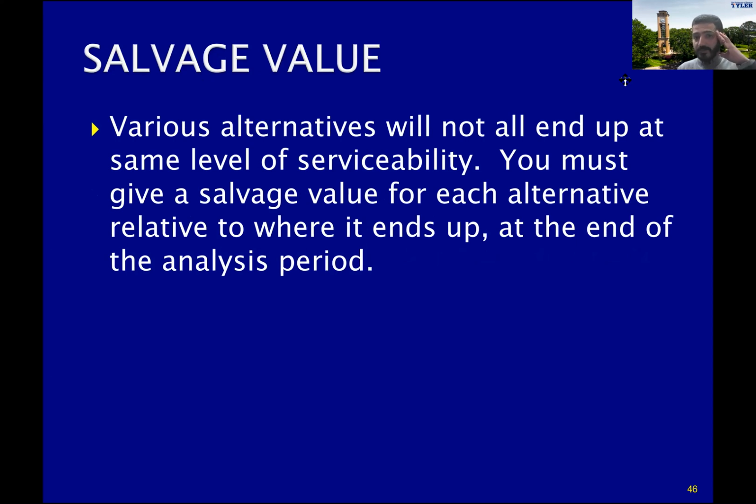Salvage value, that's also important. There are lots of different alternatives that will not end up at the same level of serviceability. So it's also important to know if I add a 4-inch overlay, what would be the salvage value after 5 years versus what would be the salvage value of a 2-inch overlay. So really here you must give a salvage value for each alternative that is relative to where it's going to end up at the end of that analysis period.